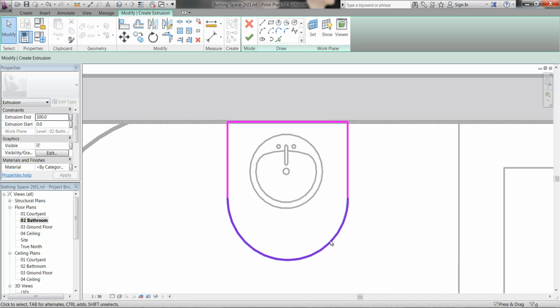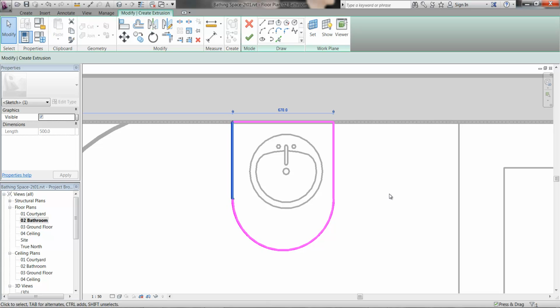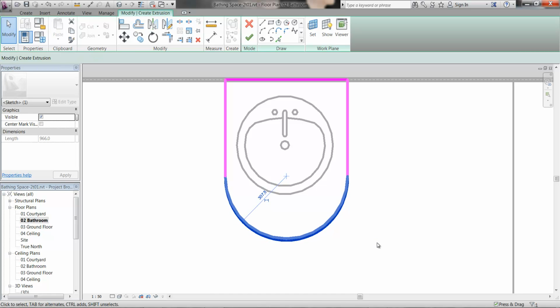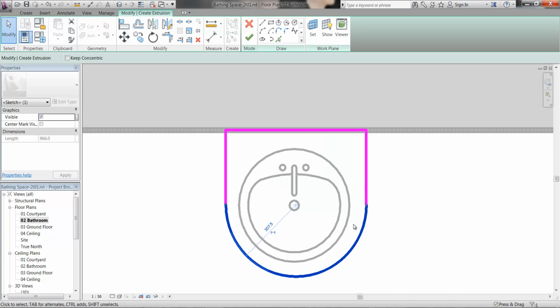And then when you're adjusting these shapes, it can be really useful using the arrows. So I'll start by selecting one of the lines, and then using the arrows on the keyboard, you can see if your shapes are connected or if your lines touch, it'll move them and keep them connected. So that you can just do with extrusion. So I'll maybe give you a quick example. So the next file I've got has it anyway, but maybe I'll just make it for you. So here you can see that I'm just using the arrows on the keyboard to make that arc smaller, and you can see that's a good way of just trying to get it to follow something else.